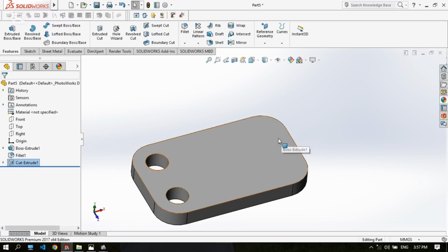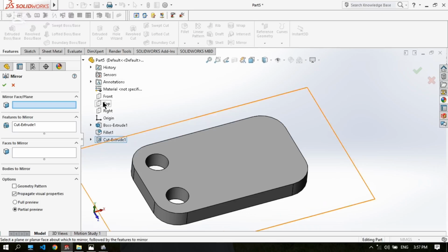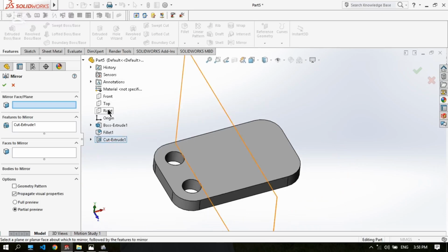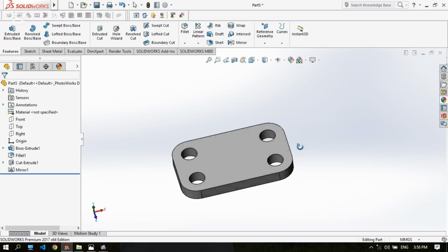And then we make these 2 holes on that side. We can use the sketch method. We use the mirror to mirror them to the other side. This is the easy method. Choose mirror there. Here, the mirror face plane. You need to fill in the plane. Be careful to choose the perpendicular plane. This is the right plane. Yes, planes. And now, if you cannot select here, choose from the previous Extrude base. Okay, hit OK. Yeah, very easily.